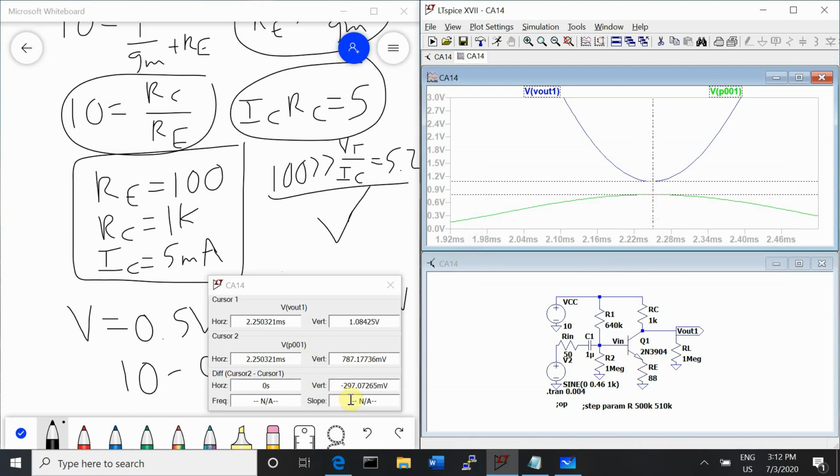And then we're right about exactly at 0.3 volts, just like we're looking for. So if we get to a point where we have less than 0.3 volts here, then we can fix that by either decreasing the gain to raise this here, or increasing the bias point to raise this here, depending on how much room we have at the top to allow us to make that change. So we're good there.